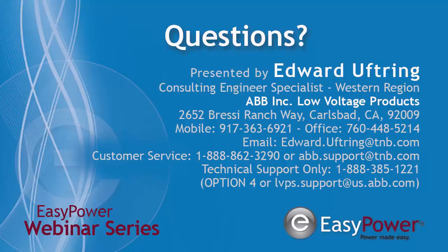As an individual component, does an MCP have a short circuit interrupting rating? Not as an individual component, it does not. There are no fusibles. That's why we have the breaker on top of the MCPs. Those are going to be your short circuit interrupting rating. So the SCCRs are not going to be there.